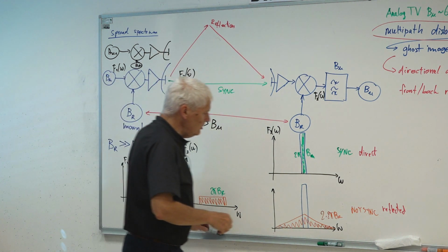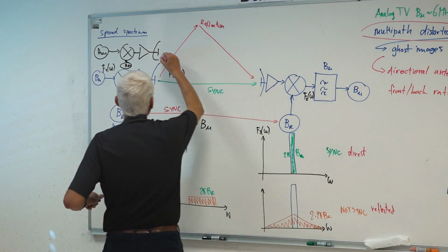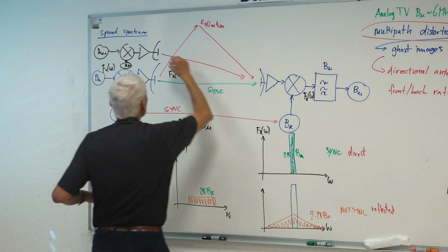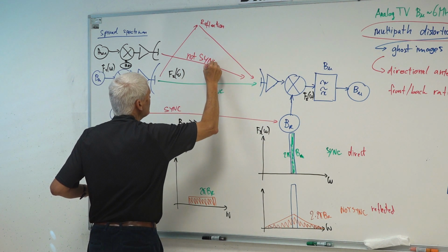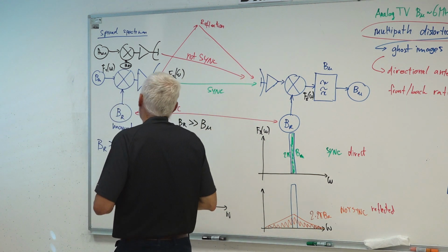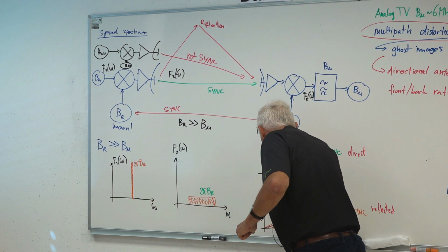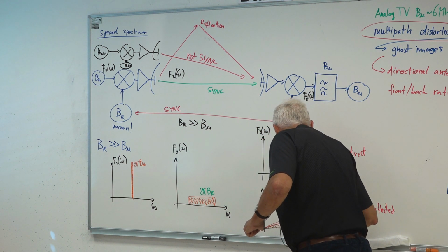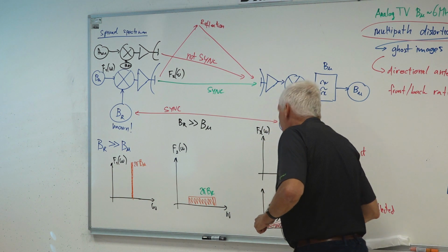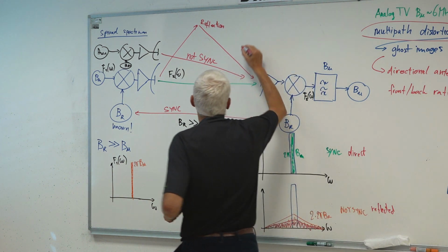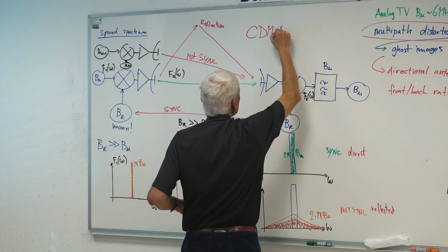This one here only causes interference because this is not synchronized. Not synchronized because it's maybe a different spreading sequence. It only causes interference, and also the interference spreads out to a much broader signal. So these things actually allow me code division multiple access, CDMA.